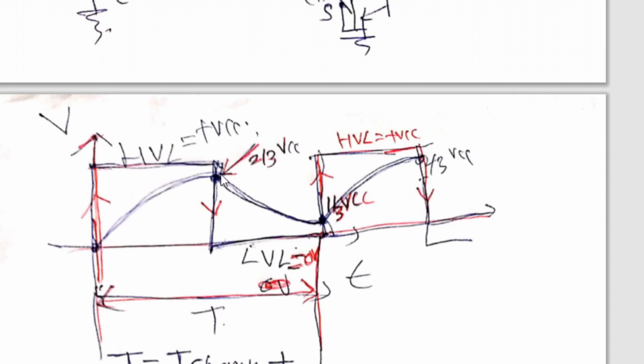Similarly, when the capacitor charges just above two-thirds of the Vcc, that is just above 10 volt, the output of the comparator changes and the output of the flip-flop also changes. So the upper terminal of the flip-flop, means Q, will become logic 0 and Q bar will become logic 1 and the transistor will go into closed switch.